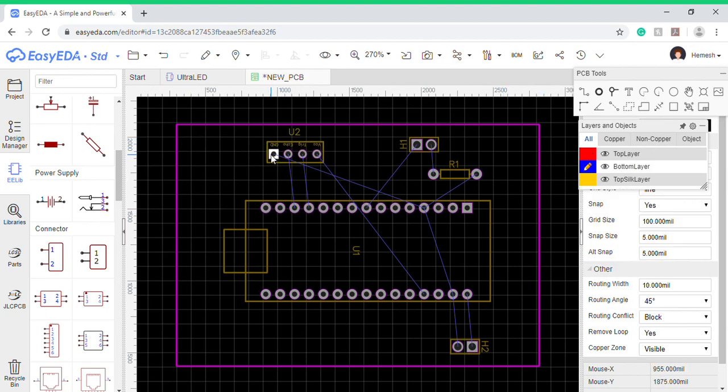Yeah, so if you click on the wire button, which is the track button, and then on the bottom layer, you can now click on any of the connections like this. It shows the PCB where to connect. I'm going to connect it in the shortest way possible. As it's very far, we don't have much to do. Yeah, as you can see, it gets connected.